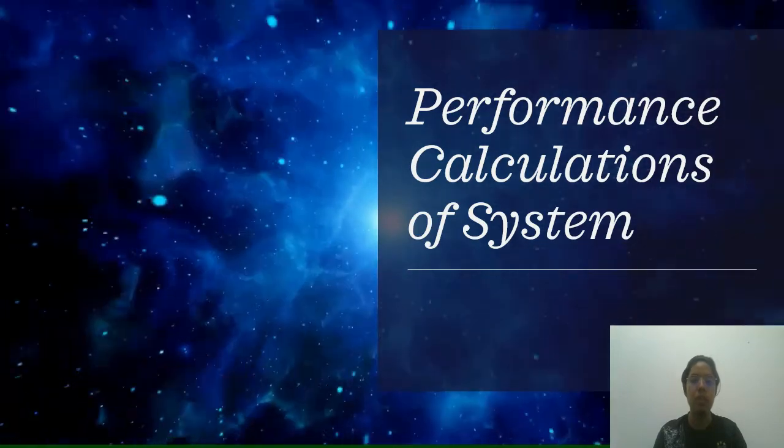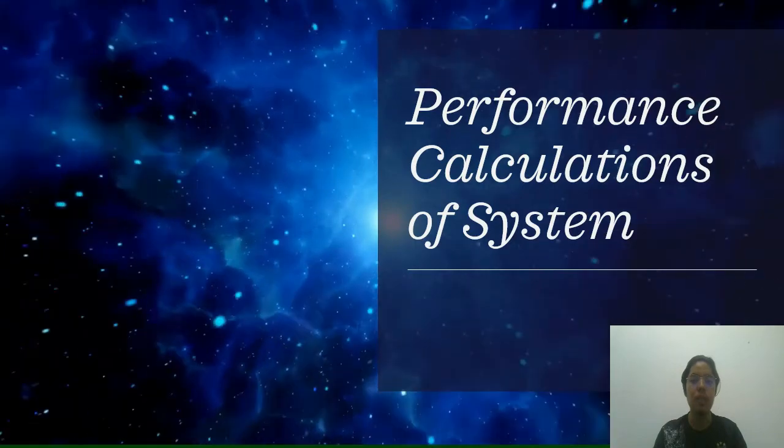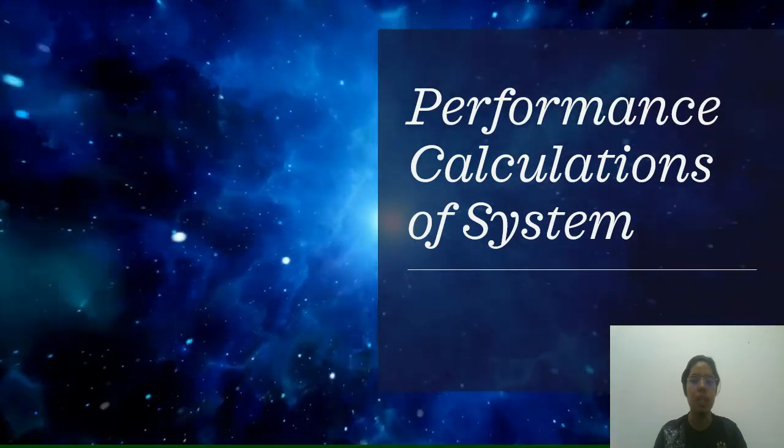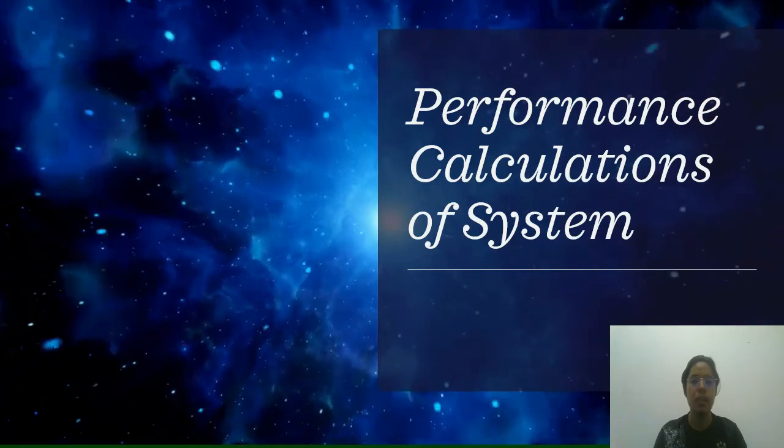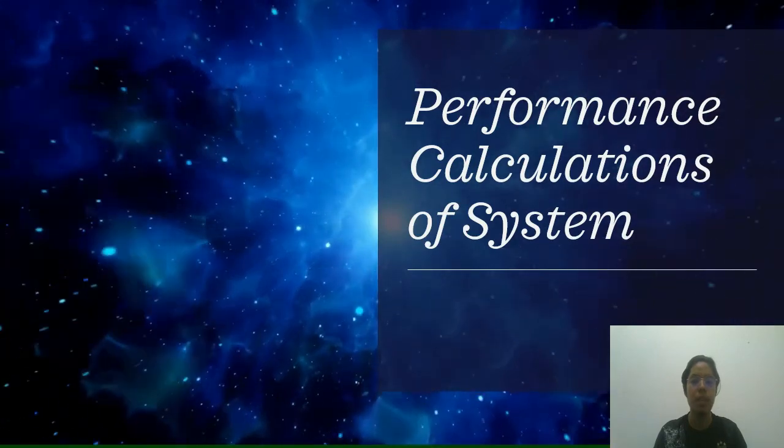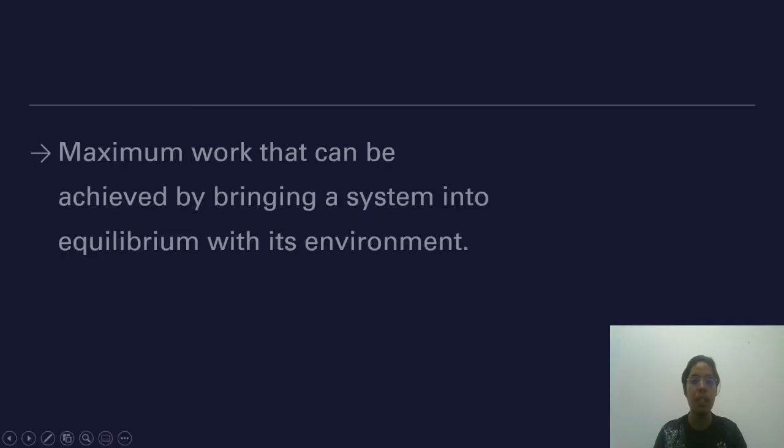To perform the calculation of a steam power plant with double reheat and feed water heaters, energy and exergy analysis can be applied to the system. Firstly, let me introduce what exergy is. Exergy is defined as the maximum work that can be achieved by bringing a system into equilibrium with its environment.